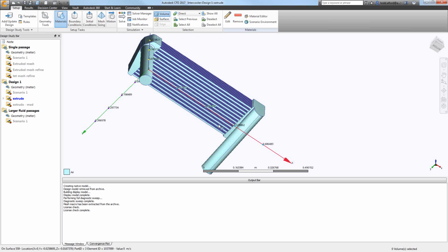But here, if we wanted to even out our flow rate so that we have the most efficient heat transfer, I wanted to have a decent pressure drop across it, which ADV5 is going to do a little bit better for us numerically. And then I'm using the standard K epsilon, because we're not looking at vortex shedding or anything like that. Once we get into those flow channels, it's a lot of straight flows.